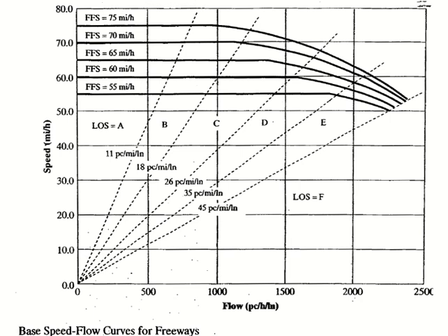From these curves you can see the end of the curve and find out the capacity, you can see the drop in the curve and find out the breakpoint. But most importantly, you can find out the level of service. You look for your flow value here and go up to the curve of your free flow speed and you can find out the level of service.